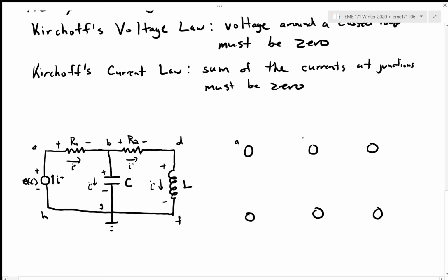And I'll transfer the letters over so that we know what's what. Right. So I have a zero junction for each node of this circuit, and that is tied to an effort at that node. We know that the zero junctions are common efforts, so I have a common voltage at each of these nodes, and we can move on to step 3.